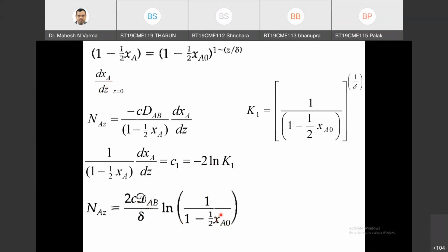So this is at xa0. This will give you local flux. Local flux means flux at one catalyst particle, which depends upon local concentration. And this local concentration is changing with the length of the reactor. If you monitor that variation in concentration, this multiplied by surface area will give you the local rate of mass transfer. That can be integrated over length to get an overall rate of mass transfer, and you will get a conversion at the end.